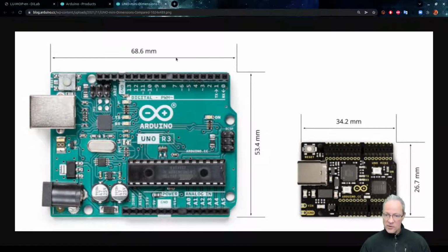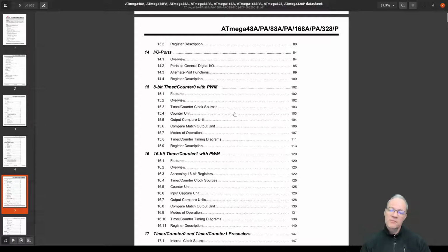So thanks to those ports, we can connect this processor to the outside world, and it talks about what kind of ports do we have. We may have just general input and output pins, meaning that you can set 1 bit or you can read 1 bit from that pin. Some pins may have other functions. We can reconfigure them to become serial ports, for example, or pulse width modulation outputs, or other functions. So therefore, we can also talk about alternative port functions here. All right.